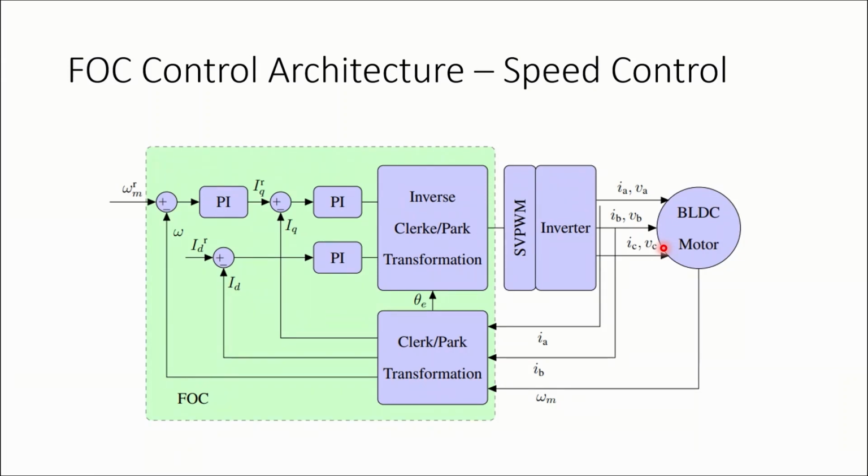So when you control the throttle, it is torque control mode, and when you give a reference speed and the vehicle is supposed to follow that reference speed, just like in this case omega, which normally represents the speed term, then that is called speed control mode. Over here, one more extra block will come into the picture: the reference speed is subtracted from the omega estimation. What is omega? We calculated it from the motor, in feedback, and this is the actual speed of the motor. This is the reference speed.